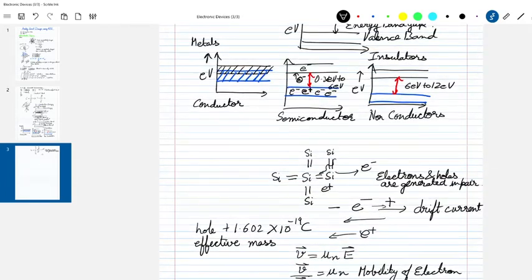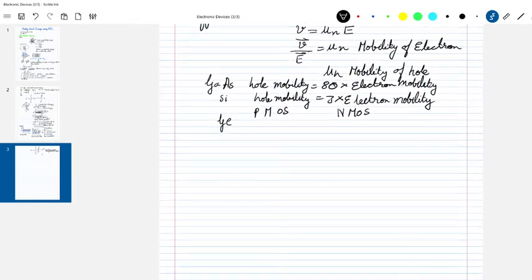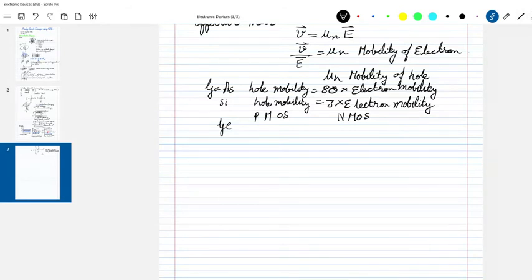Now we are going to deal with semiconductors only. Now semiconductors are going to be elemental in nature, and these are silicon, carbon and germanium, while then there are compound semiconductors which are going to be binary. These are going to be third and fifth group, gallium arsenide, gallium nitride, indium phosphide, aluminum arsenide, and stuff like that.